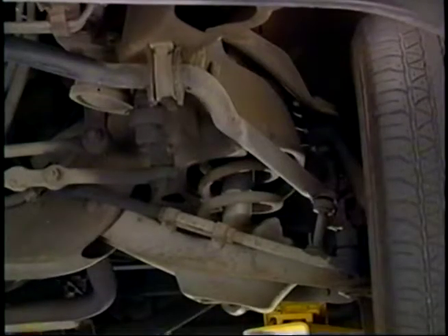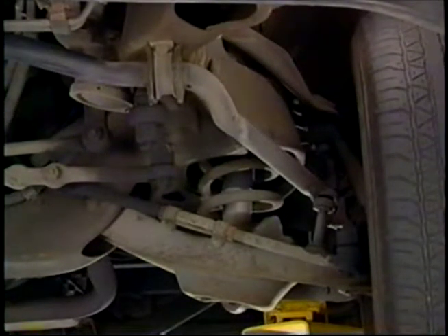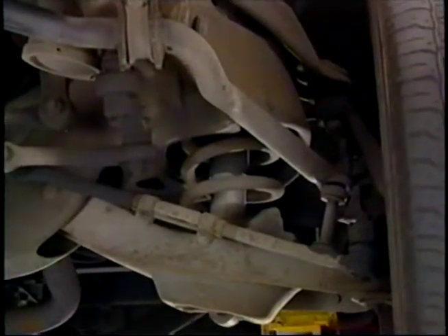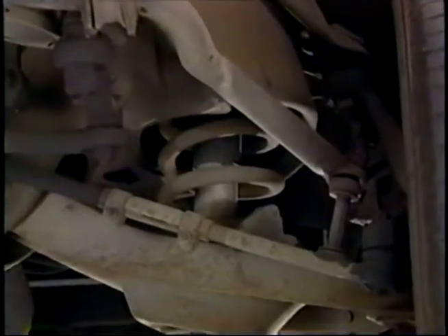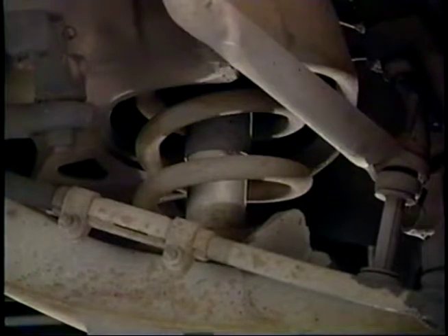Don't overlook the coil springs when troubleshooting suspension noises. Springs that have shifted in their seats or worn through the insulators will cause noise. Weak coil springs will cause the car to sag or to pitch forward on braking. Weak coil springs affect ride height and must be replaced.